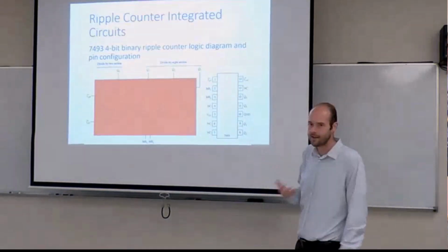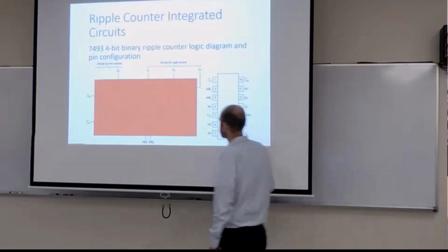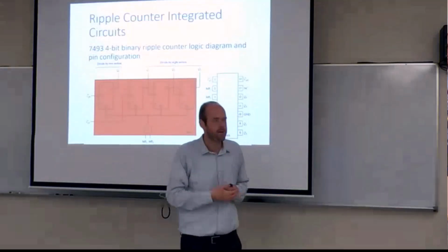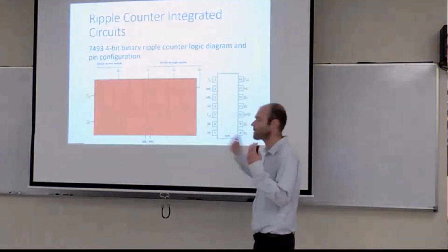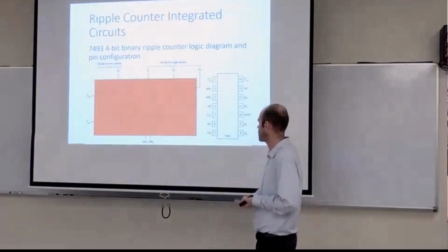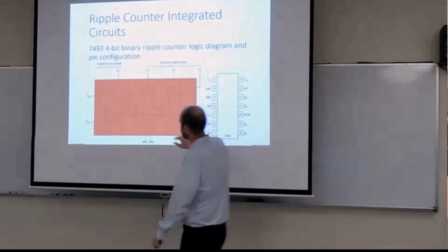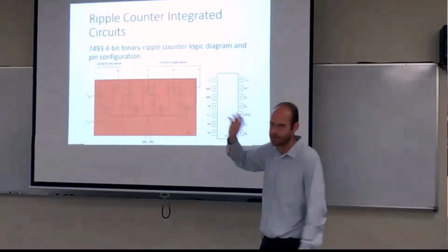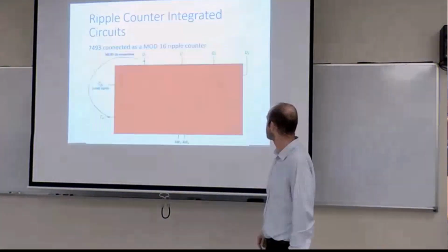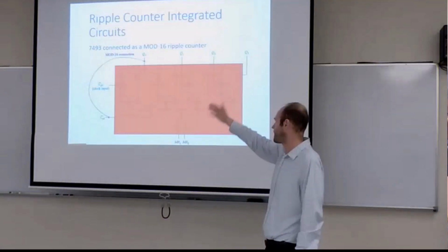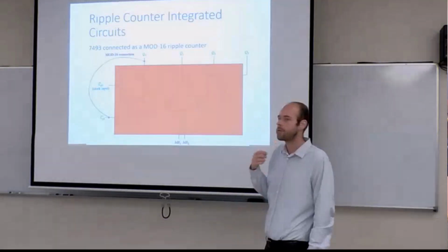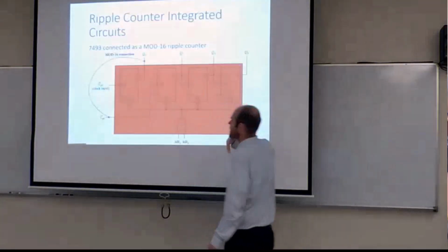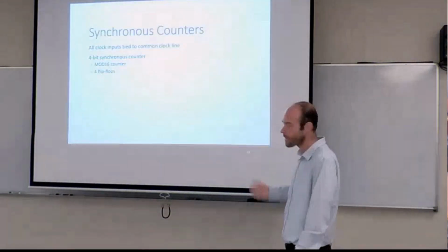For that style of chip. Obviously, in our FPGAs, they're all going to be manually created and binned together. So depending on the type of implementation you run into, FPGA versus traditional chips, you may or may not run into that. But I wanted to mention it because in a lot of data sheets that facet still feeds forward, and you'll see it in the textbook as well. And you just physically connect the output of 1 to the clock of the next. So you do need a conceptual understanding of how these 3 bits are connected, and then you can make sense of the hardware, whatever it happens to be.